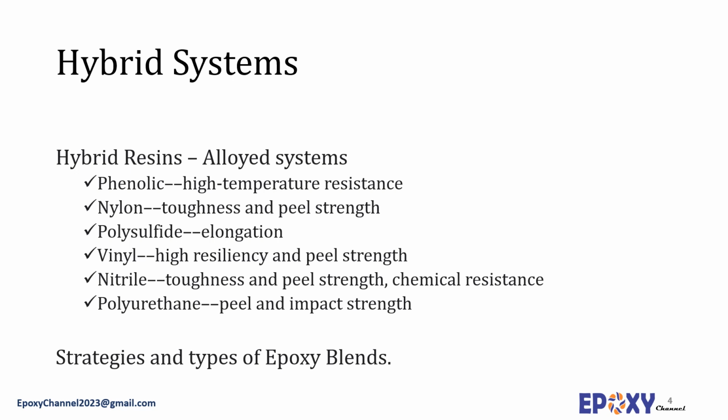Various polymers, thermosets, and thermoplastics can be blended and co-reacted with epoxy resins to provide a specific set of desired properties. At high levels of addition, these additives result in hybrid or alloyed systems with epoxy resins rather than just modifiers. They differ from reactive diluents in that they are higher molecular weight materials that are used at higher concentrations and generally have less deleterious effects on the cured properties of the epoxy resin.